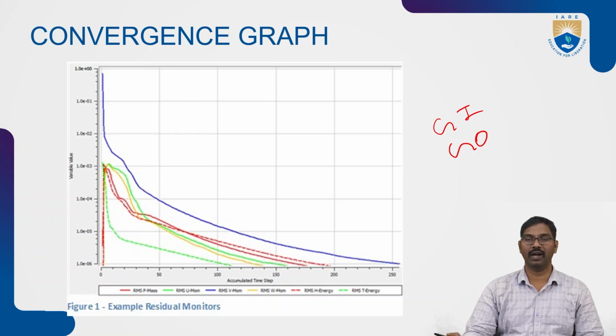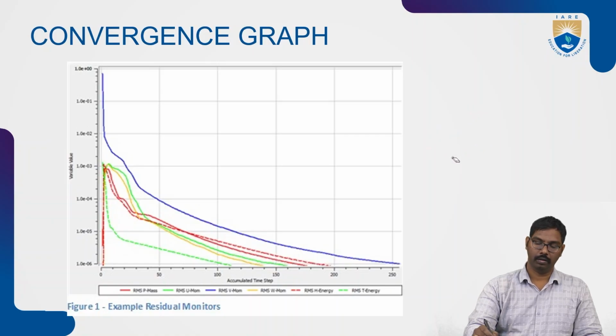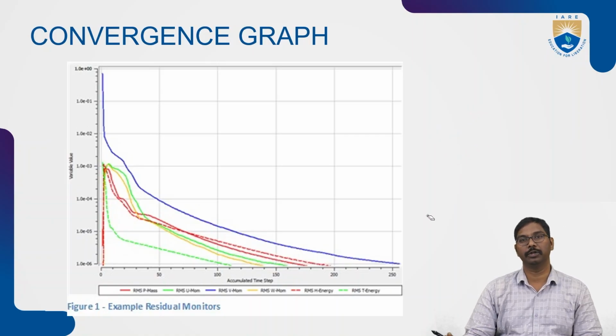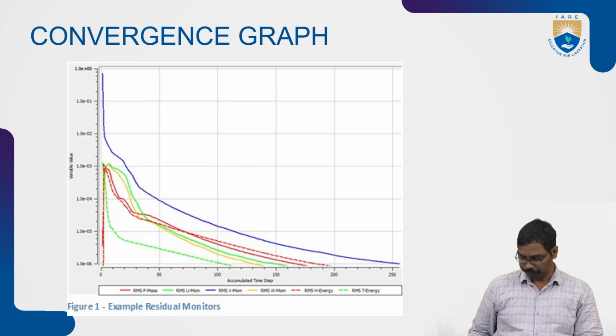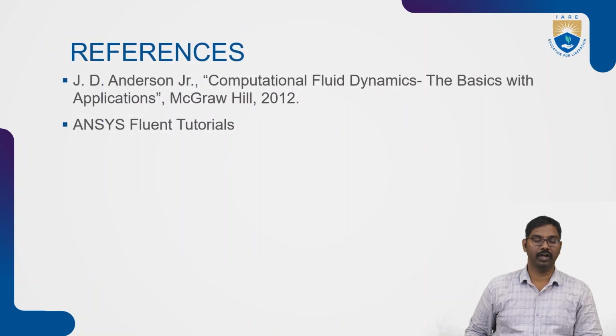But just colorful results are not necessarily correct or accurate. You have to understand the results and interpret them as per your requirement. If the streamline path, the pressure contour, or the Mach number contour is not showing you the lift or the pressure difference which you are getting, then that is not a well-posed problem. So that is about well-posed or ill-posed problems.